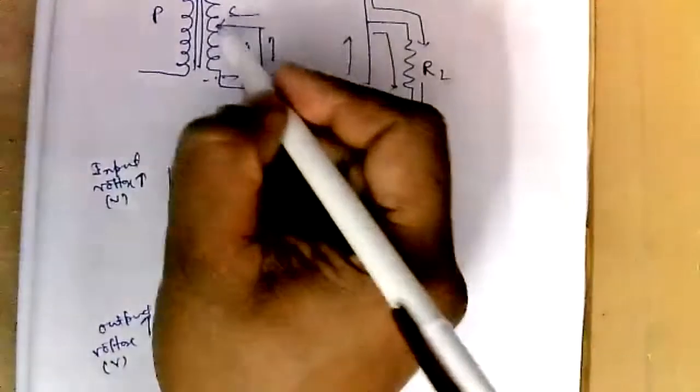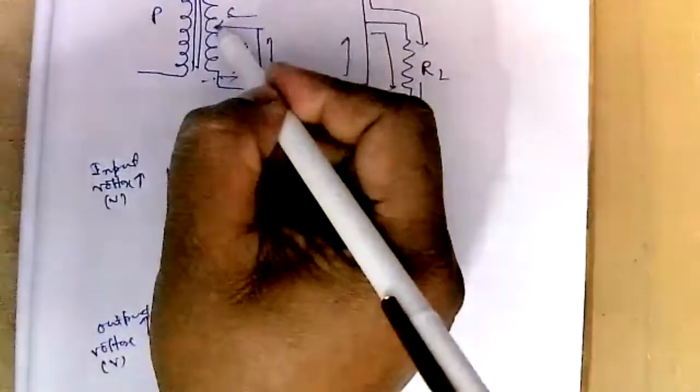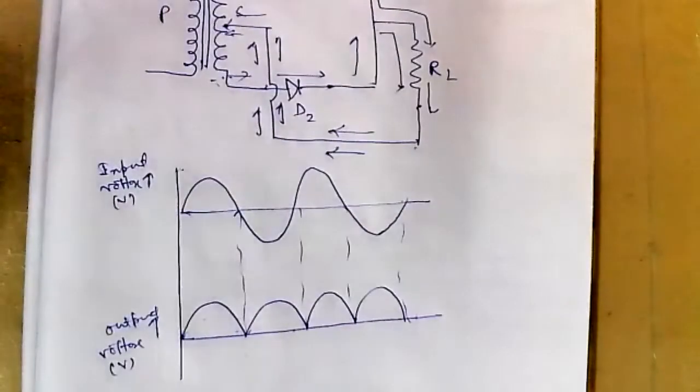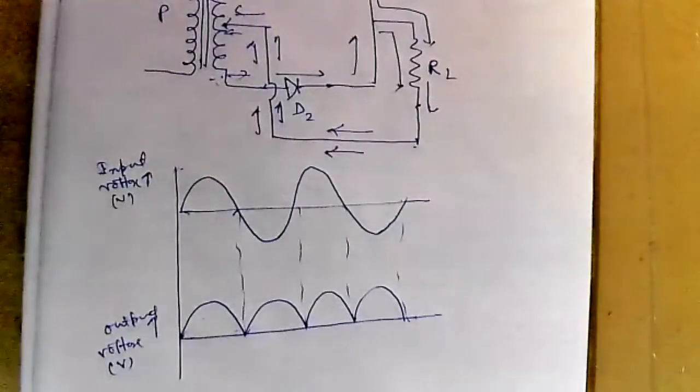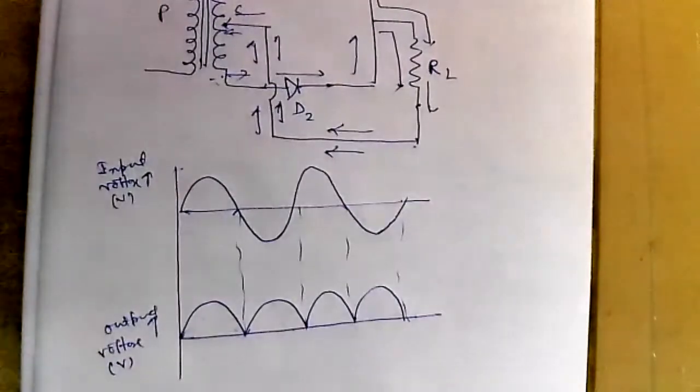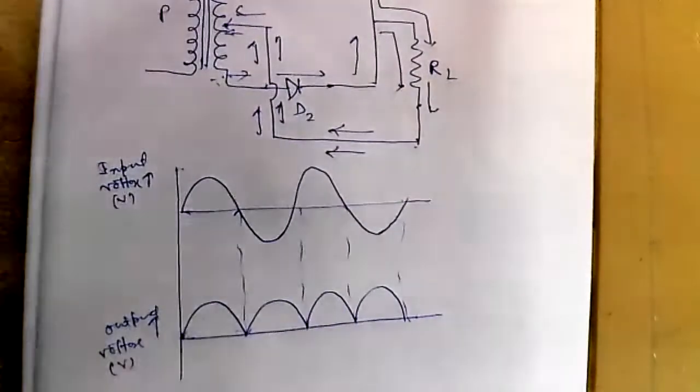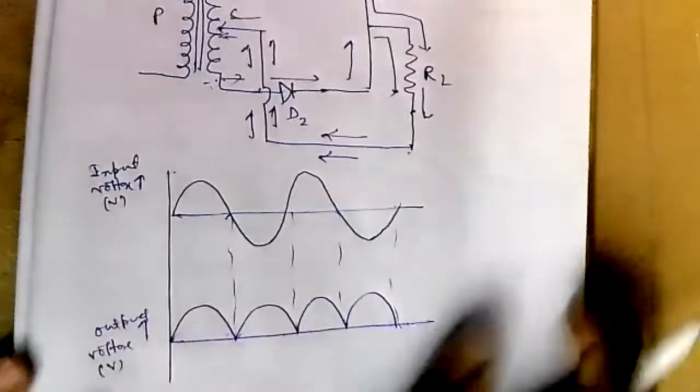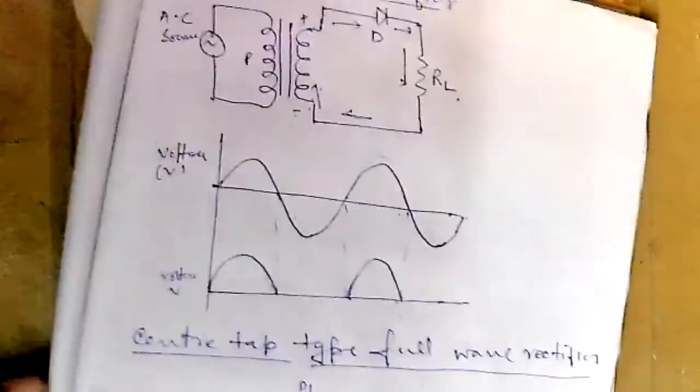But still there is a problem, as you are using the tapping at the center. So you are utilizing only half power of the transformer.